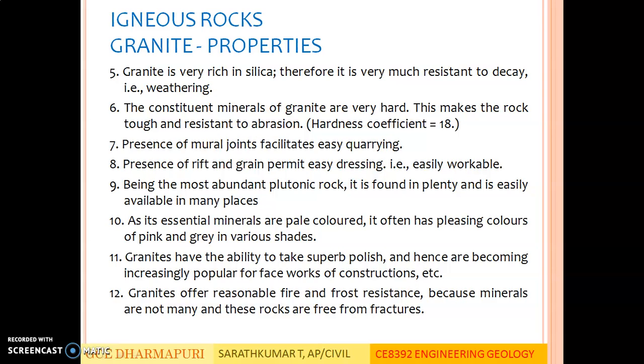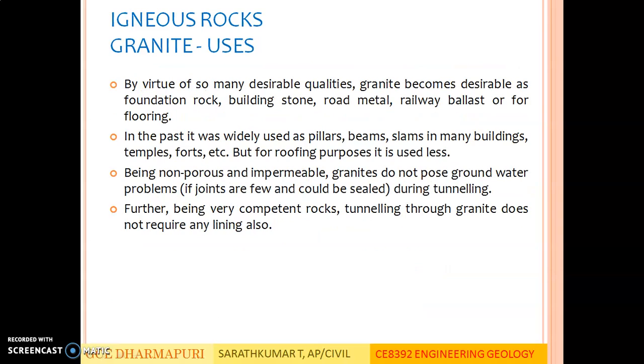Granites offer reasonable fire and frost resistance because minerals are not many and these rocks are free from fractures. As we have seen in fire and frost resistance, if the number of minerals forming the rock is less, and if the minerals have smaller grain size, it will have more frost and fire resistance. Since granite has very few minerals and its grain size is smaller, it is resistant to both fire and frost. These are the properties of granite.